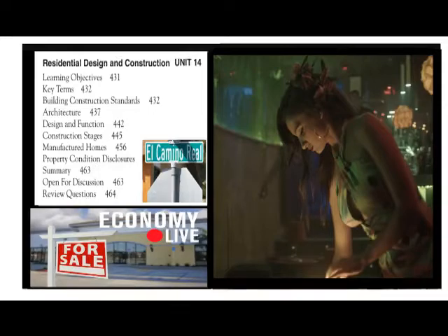In a region that has relatively mild winters, a southern exposure to the rear of the house may be desirable. Such an orientation allows maximum use of outdoor facilities, such as a patio or swimming pool. Especially on a hillside lot, the view may be the primary consideration in orienting the house. Because contemporary designs do not require rigid placement of front entry and windows, those features can be placed to take maximum advantage of the site. Often a fence-enclosed outside patio can turn a part of the house with a poor view into an attractive oasis.